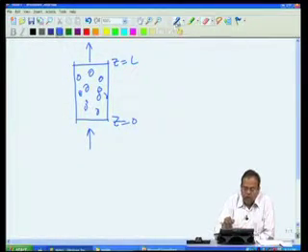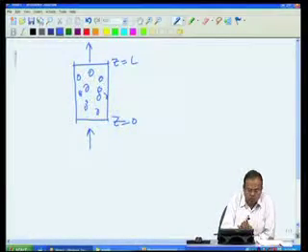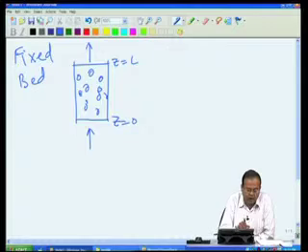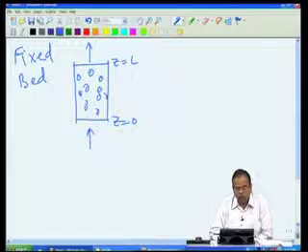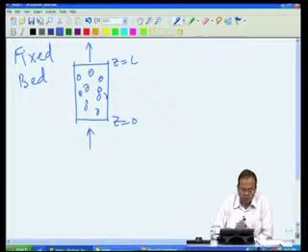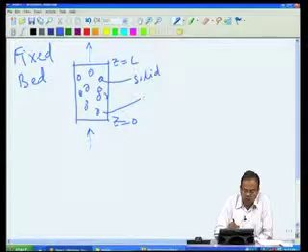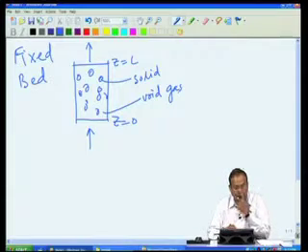In principle, the mass and energy balances for the fixed bed reactor must be the same as or similar to those of the tubular reactor. Indeed they are. However, there is one difference that we have to take into account, and that is there are two phases in this reactor, one solid and the other the void or gaseous phase, which represents the voids.